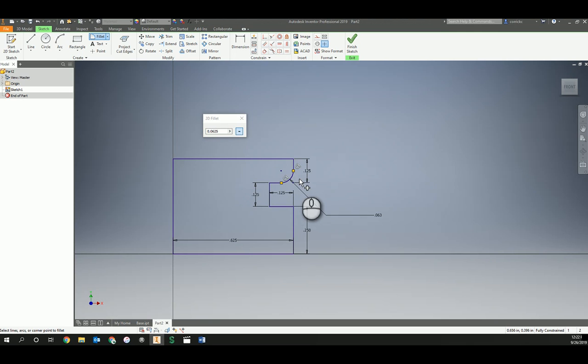We're going to talk about constraints another day. But I found it's really important to do this in a certain order. A lot of students were getting messed up. So I'm clicking the corners I want. And I'm seeing some nice constraints all the way around. Okay, so parallel constraints, tangent constraint, and that's it. Now I'm done with this command, so I'm going to right click and say OK. It exits that command, and here I have the basic shape for the base. I'm done with it, so I'm going to finish my sketch.